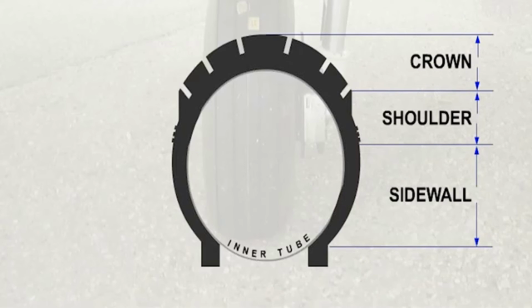To assist you, should you ever need to describe the cover, it's divided into regions or sections as illustrated here. The tread of the tyre is situated on the crown and shoulder section. The sidewall allows the tyre to be flexible, and the bead is seated inside the flange of the wheel. Note that the term tread is applied irrespective of whether the rubber is plain and smooth or moulded on a block pattern. The most popular tread pattern is that termed ribbed. It's formed from circumferential grooves around the tyre.